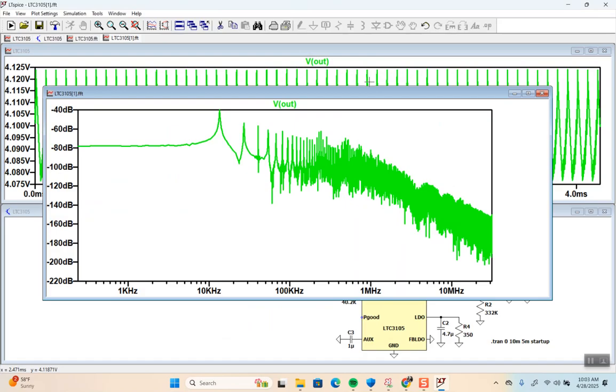All right. So I see something at 10 and all of that. So if I want to get rid of those harmonics, right? What kind of filter? Low pass. Where do you think it should be? 10 megahertz, 1 kilohertz? Where should I start attenuating?